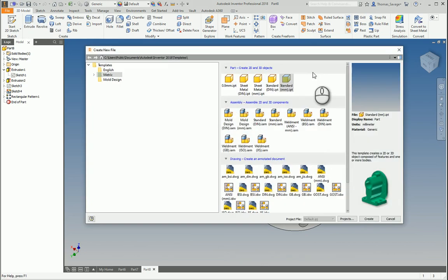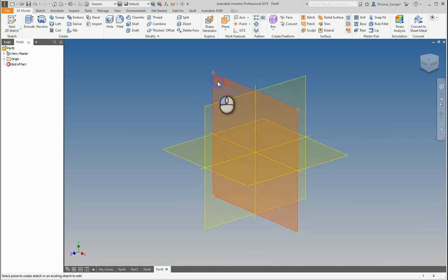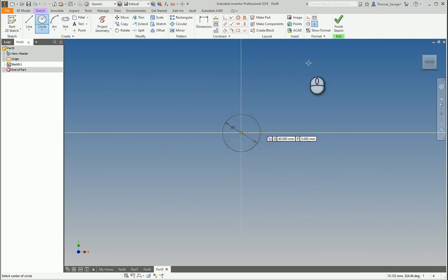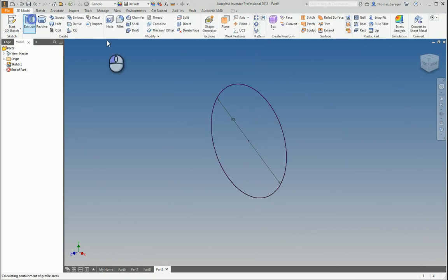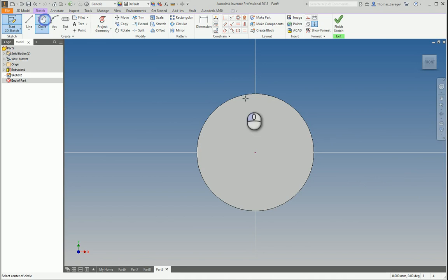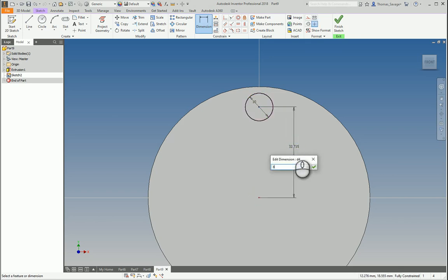Now we'll look at circular pattern. We'll start off with drawing a circle with a radius of 80. So a diameter of 80, sorry, not radius. Now, what we'll do is we'll draw, it doesn't have to be a circle, it could be a square, it could be anything, but we'll do a 10mm diameter hole. Line that up, dimension it from this center point to 30.